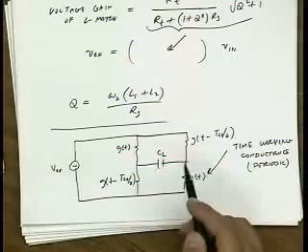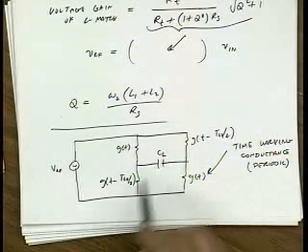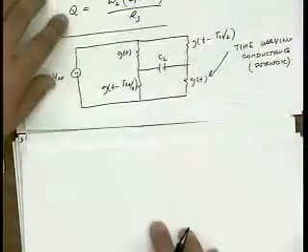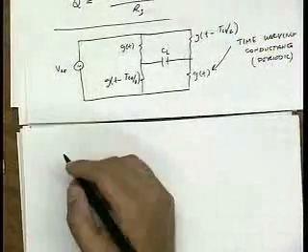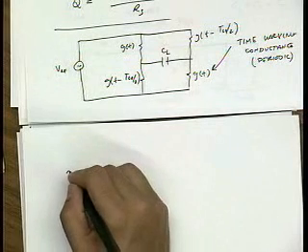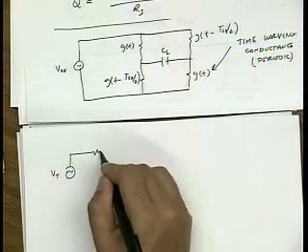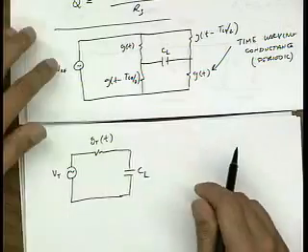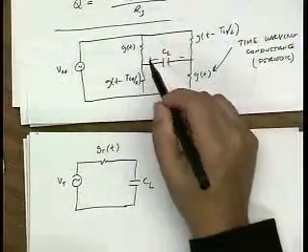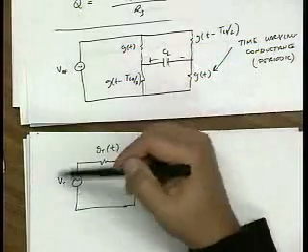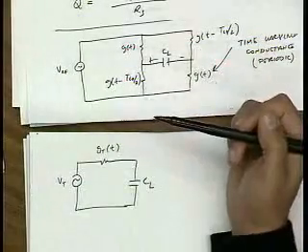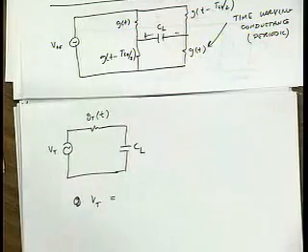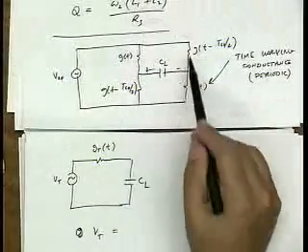Remember, for a down conversion mixer, I'm going to put a filter at the output to pick off the down converted component. And so now I can basically write some equivalent Thevenin voltage and some Thevenin equivalent resistance driving the load. So from the load's perspective, if I look back, I just see some equivalent RF voltage VT and some equivalent source, let's say GT. Okay? And the Thevenin voltage is basically the voltage divider, this voltage divider minus this voltage divider.